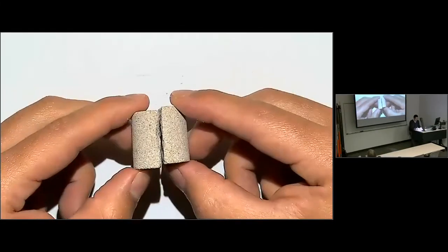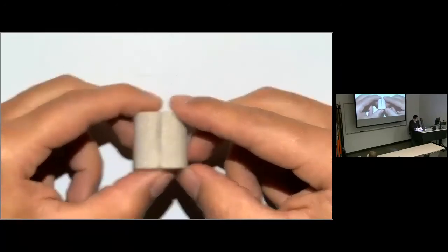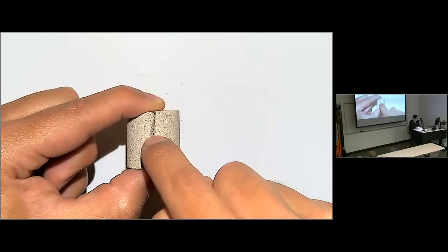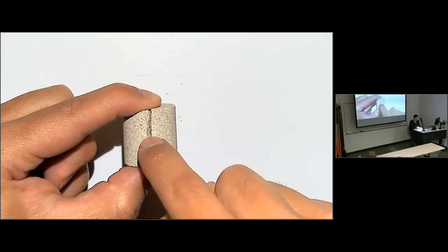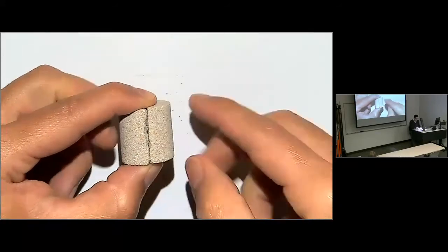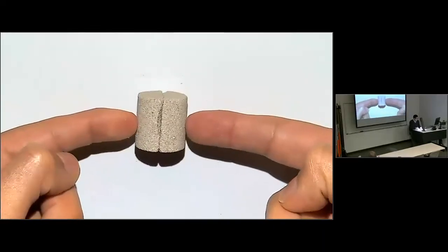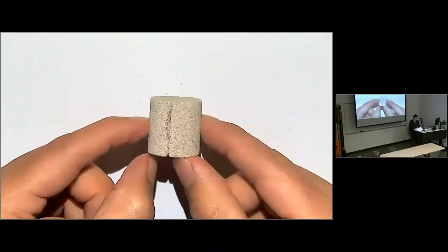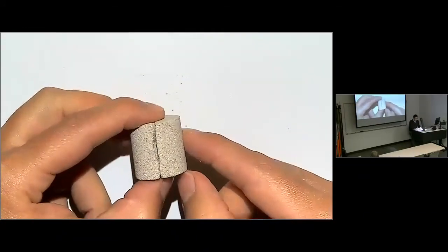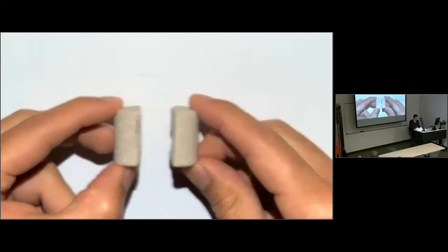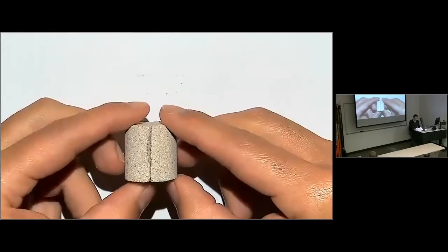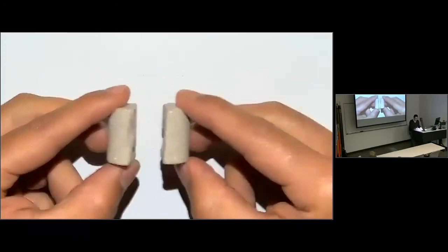So for example, if you were to inject fluid in this fracture, and if you had the same stresses in this direction and in the perpendicular direction in this one, the fracture would tend to open a lot easier in this direction than in this direction, just because of the anisotropy of the strength properties.